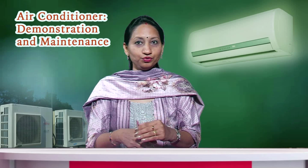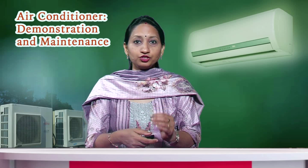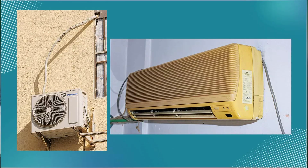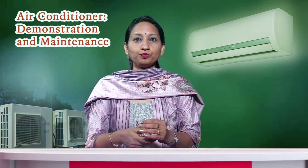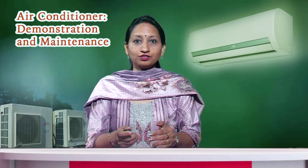For the condenser unit, you can either place a piece of plywood on top of it or use a wrap to cover the entire unit. However, make sure to remove the cover before the AC season starts. The unit is designed to be outdoors and withstand rain, so wrapping it will not affect its operation.